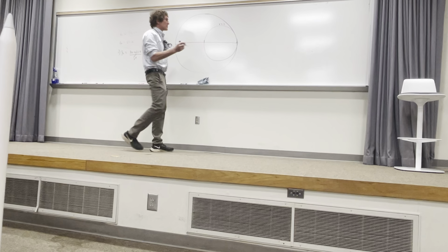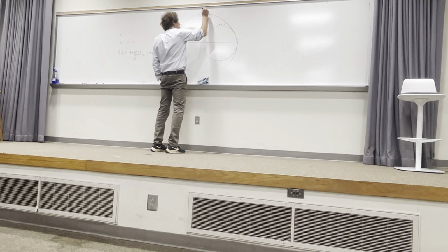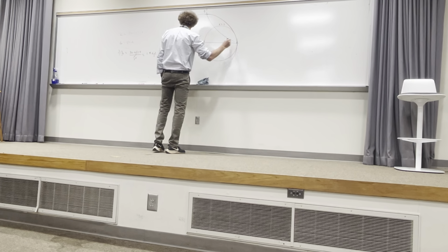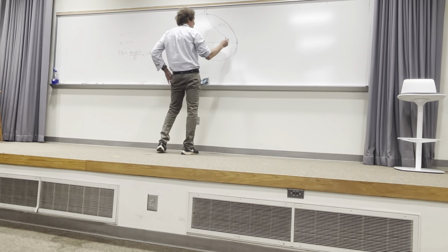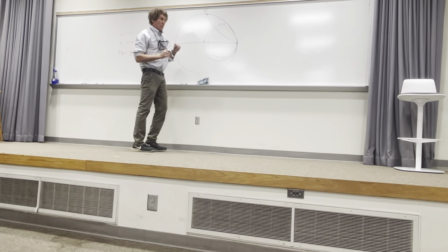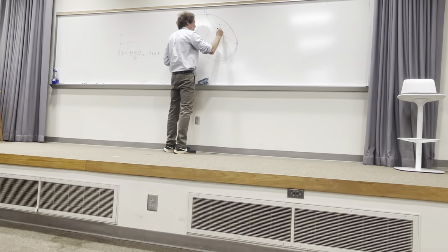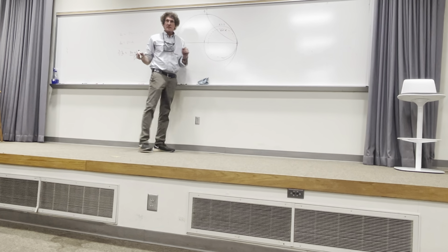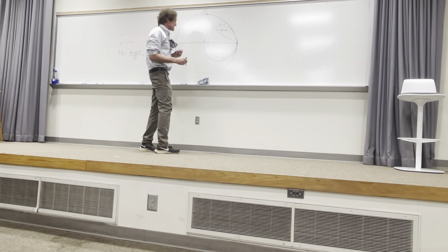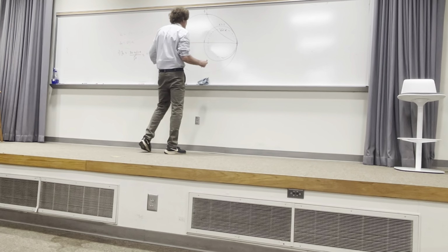So I know that these are my markers that I use. This is j1 here, and this is the 1 circle. So if I'm looking at 1.4, it's going to be a circle about here. You may have to estimate it on your Smith charts. So that'll be the r = 1.4 circle, about. Can you all see that, class? Just making sure everybody knows how to locate the first point. You have to be able to do this to go on. Clear on that one? Now, after that, the next thing you have to do is locate this j2.2.